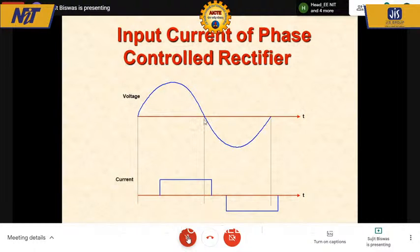Here we have two problems. First of all, the current waveform is almost rectangular. Therefore, it has a lot of harmonics in the current waveform. So that is going to create harmonic problems on the system. Secondly, you will notice because of phase control, the zero crossings of the current are far away from the zero crossing of the voltage.